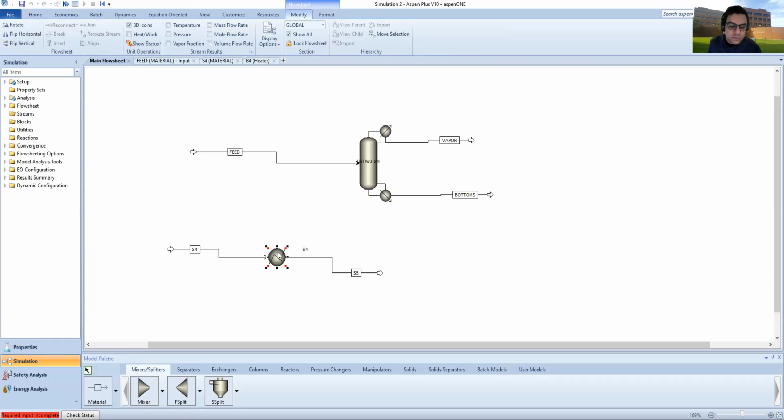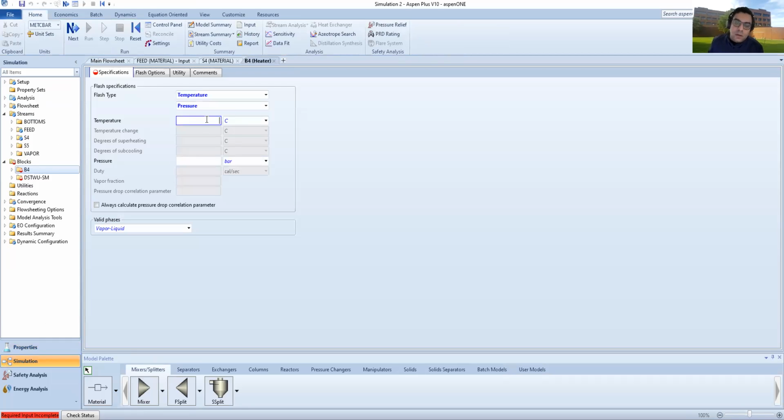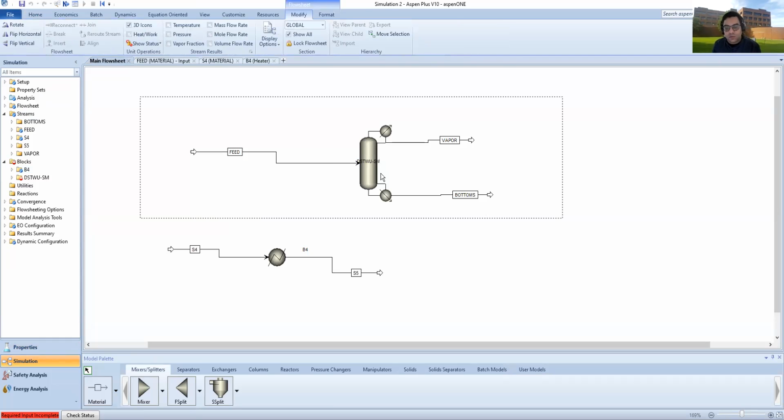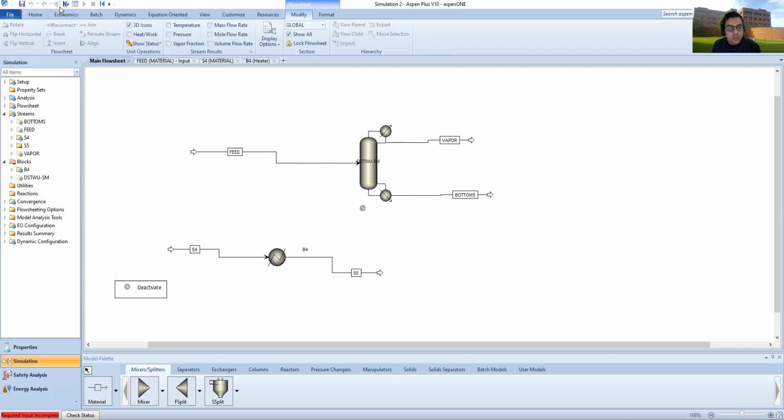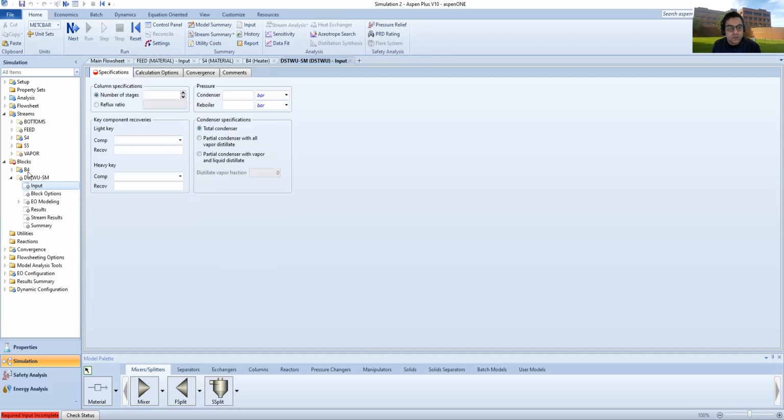And you click on your heater and you're going to run this heater at this temperature. So if I run my heater at, we said 67 and a quarter, 0.25, and we said the pressure was 1 bar. Is it 1 bar? Let's skip, no, we want the pressure to be 0. So you have no pressure drop. If you set this parameter 0, it's not going to change the pressure. So I'm going to set it to 0. Then I'm just going to run it to show it. So I'm going to deactivate these guys here. And then I'm going to run the simulation just to get some results for here.